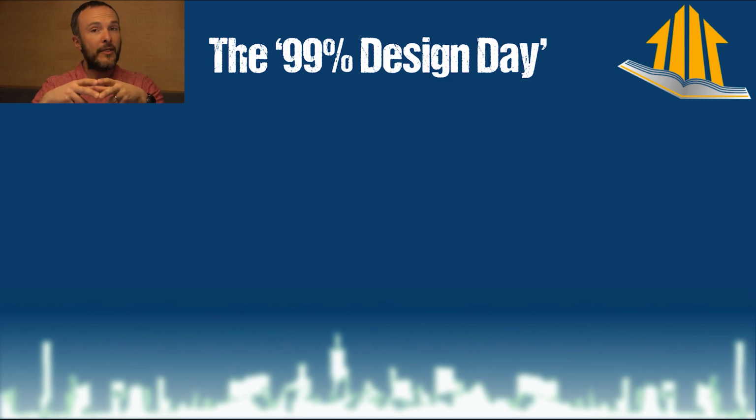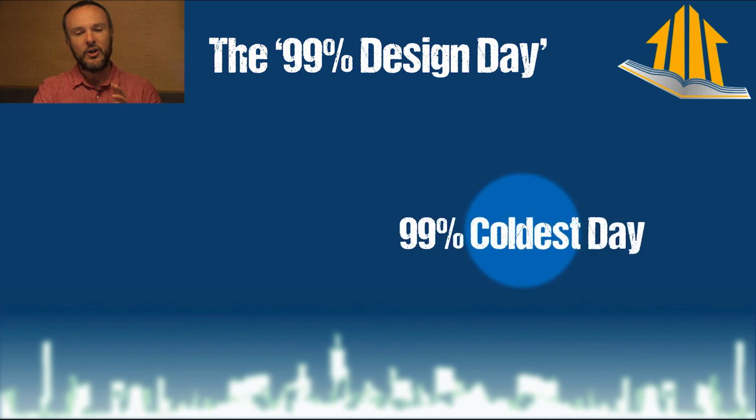But we don't use the absolute hottest from records that are kept. We use the 99% hottest or coldest. That's really important. So you want to pick the 99% coldest day. And again, you can find all of this stuff online.